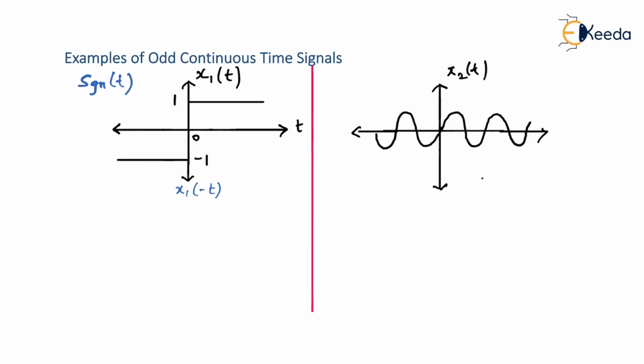And I'm sure you remember how we do time reversal. We shift the right hand side part characteristic to the left hand side and the left hand side part characteristic to the right hand side. So what will happen? You will have now plus 1 here and you will have minus 1 here. Is that right? So this is step number 1, that is what we call time reversal.